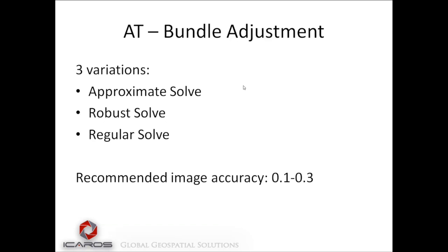Special attention should be paid to image accuracy values. Recommended values for image accuracy are 0.1 to 0.3 when running approximate or robust solve, and 1 when running regular solve.